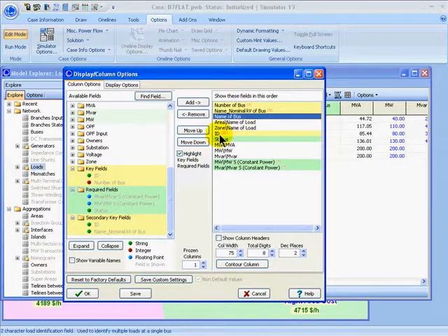The load ID also has in parentheses the number 2, which identifies it as part of the primary key. But the ID also has in the parentheses the letter B. It has actually the 2B in parentheses. And the B refers to the fact that it's part of the secondary key field, along with the name and the nominal kV of the bus. That has the A in parentheses.